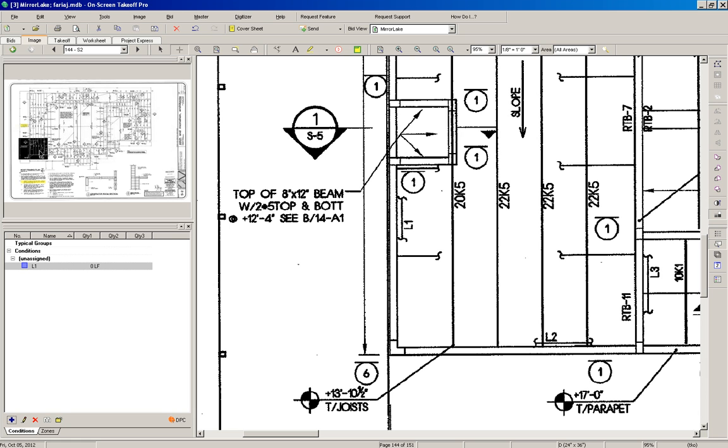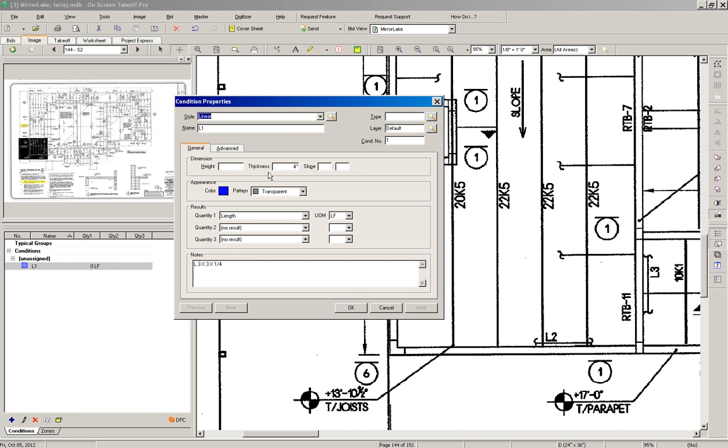Fastened to concrete tie beams with 5/8 diameter Hilti bolts or engineer approved substitute at 1 foot 8 inches center to center, max spacing. I don't know what the next part is, but we know how separate the bolts are to fasten that L to the wall. So we go ahead and we have L1.